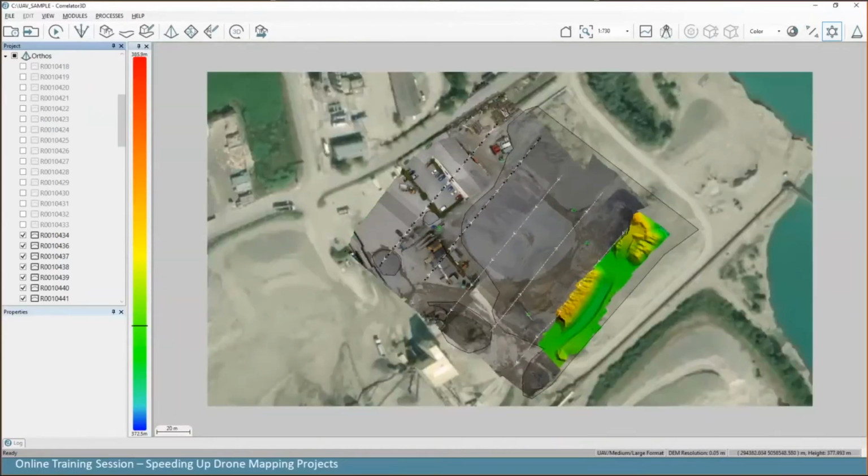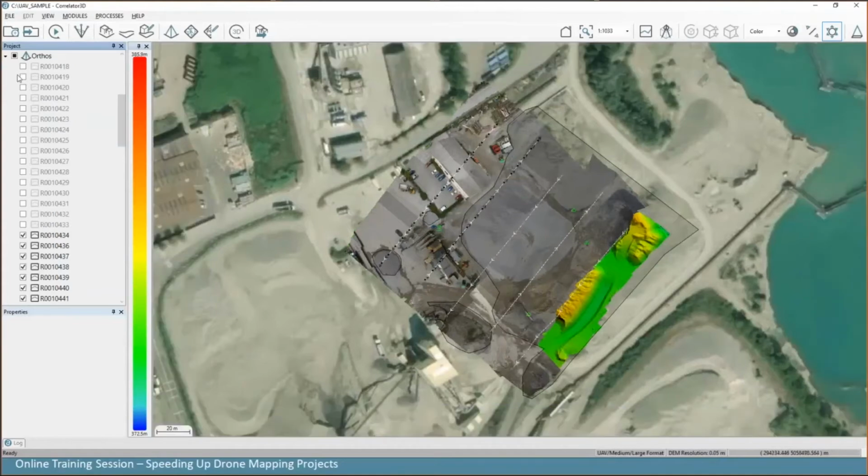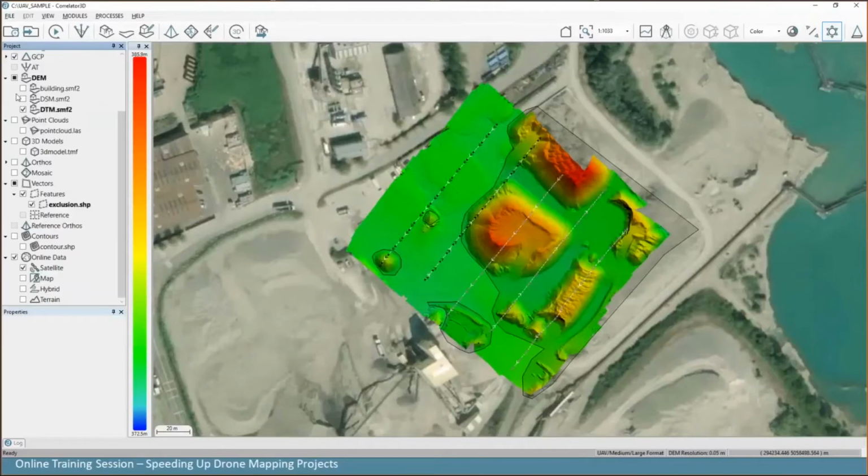One thing to notice also is if you want to manage multiple ortho folders. Let's say you want to have two sets of orthos, one for those two lines, and then one for those three lines here. So what you should do is derive your surface, your terrain model, for the whole project. Then you can disable those three flight lines, generate the orthos from those two lines, and they will appear in your ortho folder here. Once this is done, you want to change here the ortho folder and create a new one that will contain the rest of them.